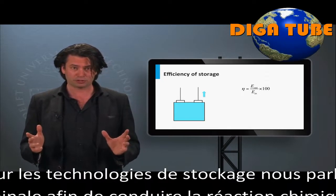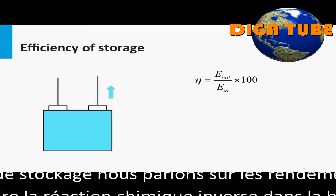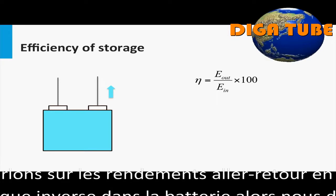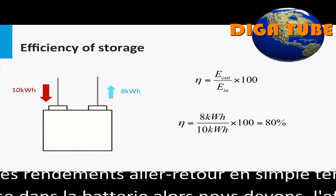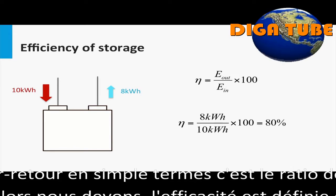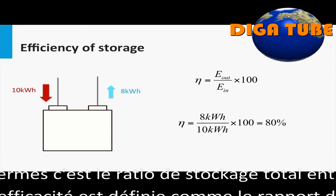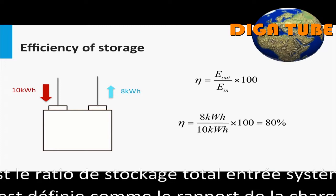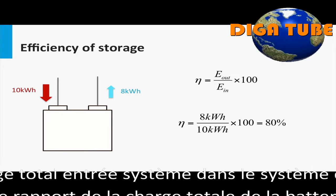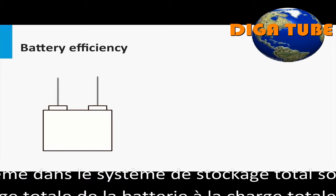In simple terms, it is the ratio of total storage system output to the total storage system input. For example, if 10 kilowatt hours is pumped into the storage system while charging, and you can effectively retrieve only 8 kilowatt hours while discharging, then the round-trip efficiency of the storage system is 80%.